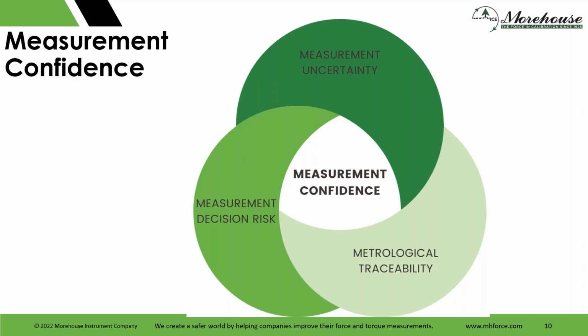How do I know the measurements my company's making, your company's making? How do I know that they are the correct measurements? And we need to get our measurement uncertainty budgets done correctly. We need to follow the rules of metrological traceability, make sure that our uncertainties, the reference standards, and we have that documented unbroken chain of calibrations, each contributing to the measurement uncertainty.